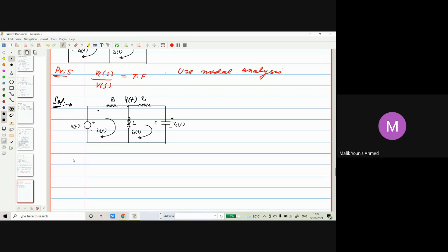Okay. What we will do first, the first step is to convert the network to Laplace transform. You have to convert the network into Laplace transform, for the circuit variables and then the voltage sources, whatever circuit variables we have, and any impedance that is there, we have to convert this.